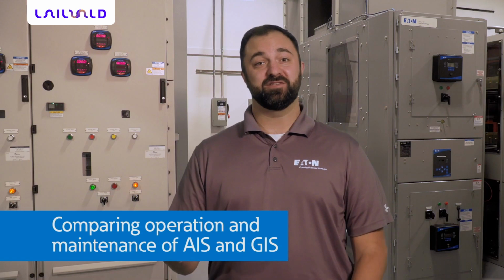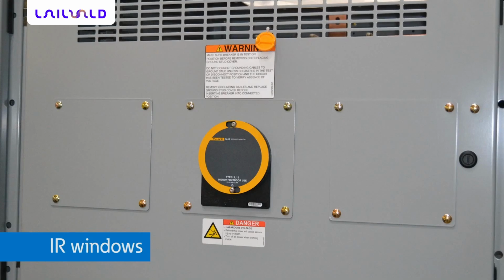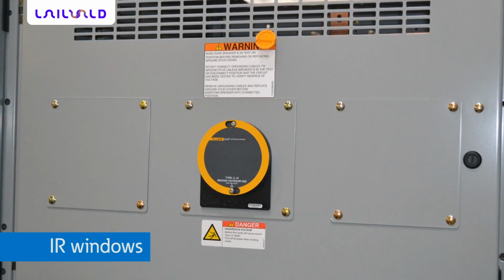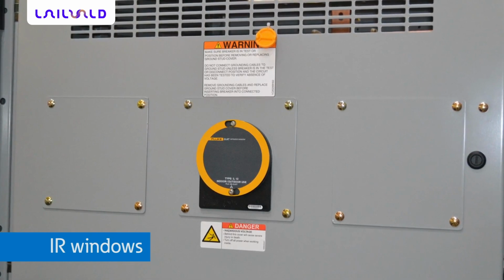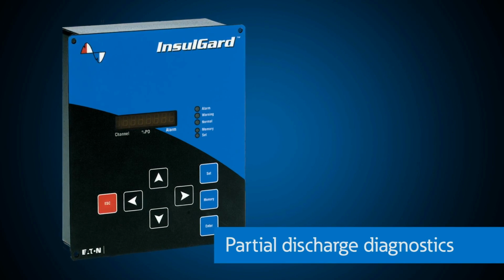Looking at operations and maintenance features between AIS and GIS, there are differences in construction that can impact scheduled maintenance. Because AIS has components exposed to debris and the environment, more periodic maintenance activities are required to ensure proper operation of the assembly. Traditional methods include installing IR windows to check for hotspots on cable and bus connections that could be signs of loose connections and lead to an unplanned downtime event. Predictive maintenance solutions are also available for AIS that include partial discharge and continuous thermal monitoring.